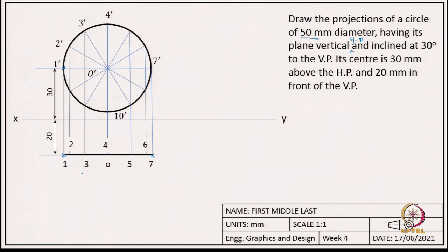The reason why we are looking at these 12 points is that we will trace these 12 points from the circle to the ellipse. Then it becomes easy for us to draw the ellipse, because we just need to connect those 12 points to draw something looking close to an ellipse.